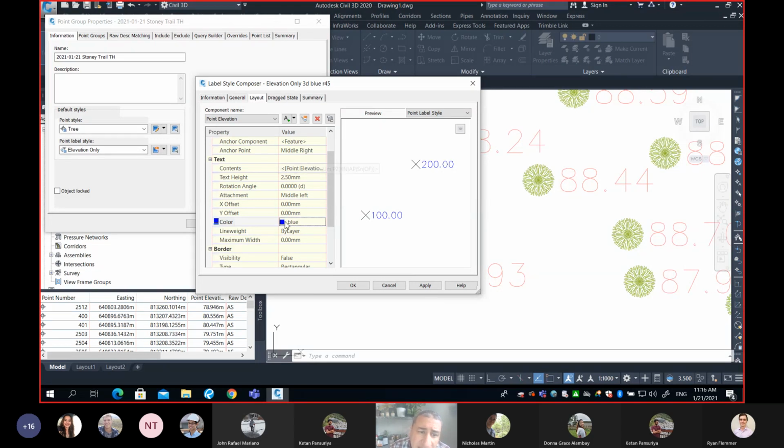Okay. Is there anything else I can change here? For example, remember, if you look at my target, I'm asking for 45 degrees rotation. Right now, the rotation is 0 degrees. So let's go ahead and type in 45 here. Once you move your cursor to any other cell, you can see the elevation has been rotated by 45 degrees.